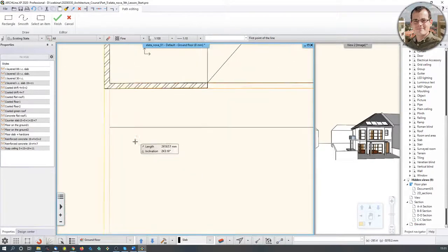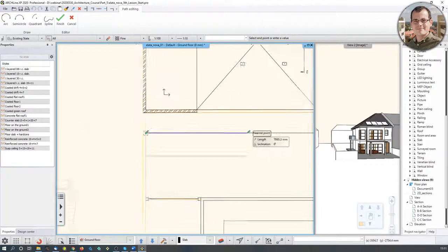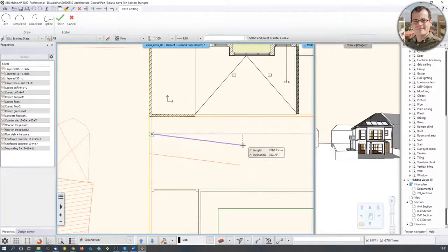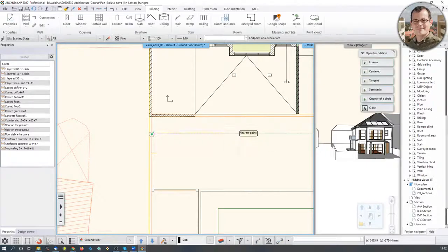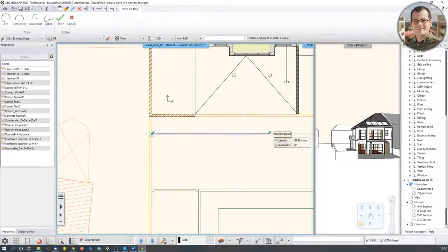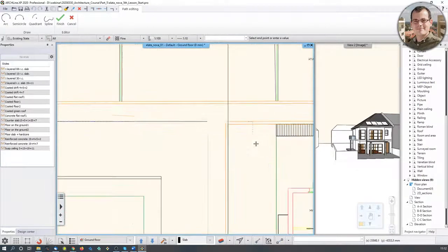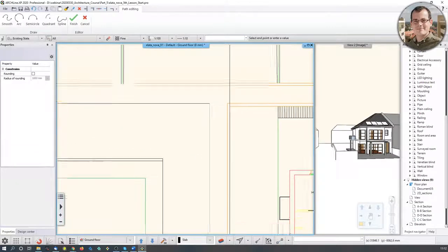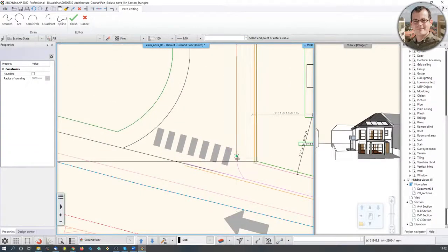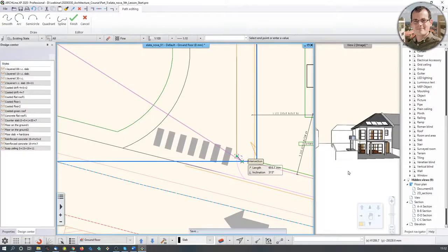Now here's how we sketch it. We click on one of the starting points and I start to draw, but you see the slab part is now positioned on the right hand side of my reference line, so I'm just going to hit F5 again, and it's going to be put on the other side. So what I do, I sketch to the points I want to trace over, just like that. I think this is all right.